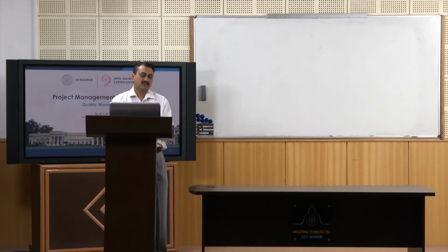So, first of all, in failure mode effect analysis, you should know what are the possible failures, right, and what is the probability of occurrence of those failures, how severe those failures are, isn't it, and then on the basis of all those things we will calculate something called risk priority number. In fact, in next slide it is there. So, you should calculate risk priority number for every potential cause of failure, right.